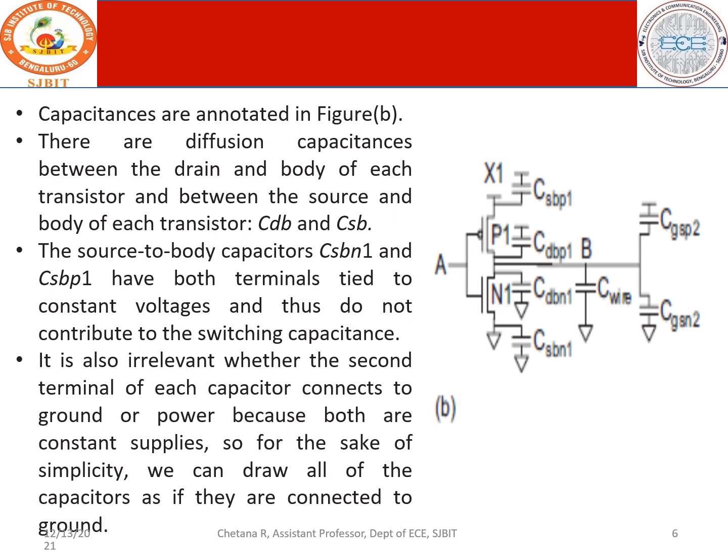Now we are talking about the load. So this is the load. Only at the load always please consider the gate capacitances. Gate capacitance, as I have already shown, is nothing but an input of an inverter. So you have PMOS on the top and NMOS in the bottom. Therefore you have the gate capacitance of PMOS P2 and the gate capacitance of NMOS N2. So the gate capacitances are considered at the load and diffusion capacitances are considered at the driver.